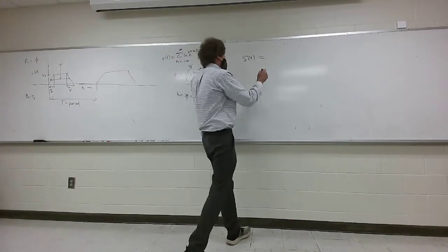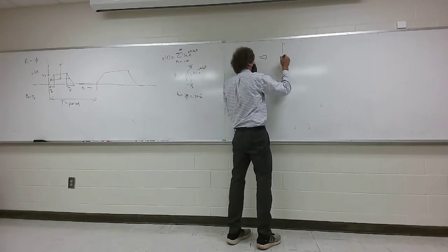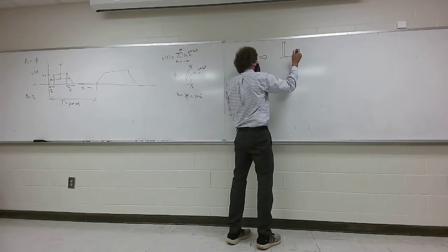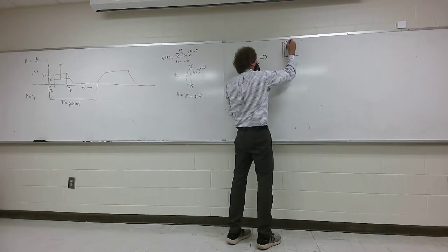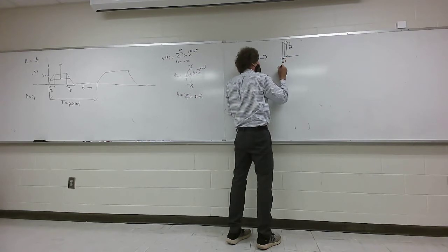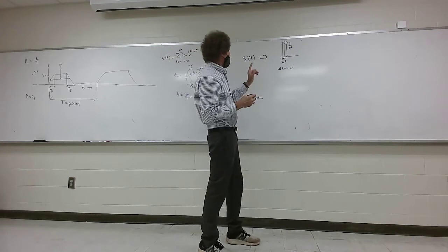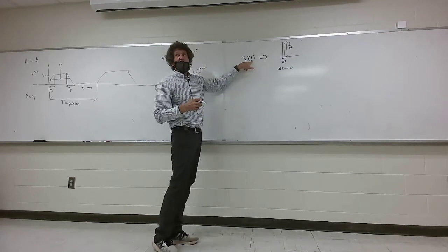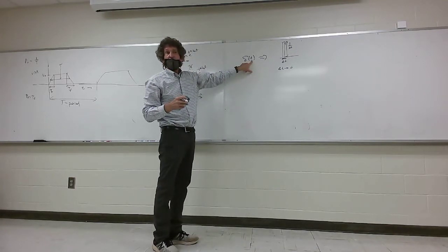So mathematically, it looks like this: the height is 1 over delta t, the width is delta t, and delta t is going to 0, right? And it's always centered at the point where the argument goes to 0. Y'all follow me? That's the delta function in a nutshell.